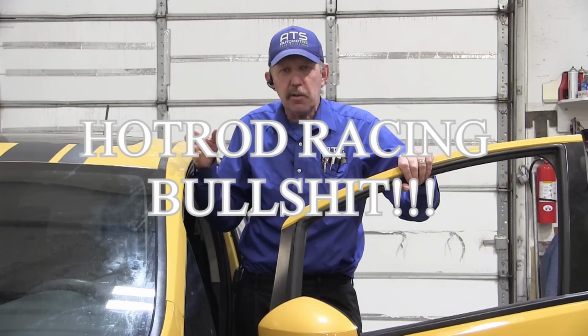Like I said in the very beginning, I said that the injectors couldn't be the problem because they're linear. But now I understand how they control these injectors. I could have a stepwise change. So we're going to get the shop to pull those injectors and check them. Okay guys, we're back over at the shop. And the shop pulled the injectors out and checked them, and the injectors were absolutely the wrong injectors.